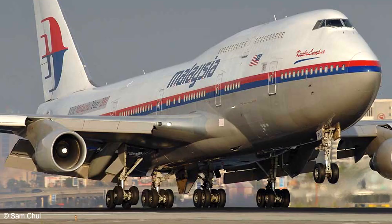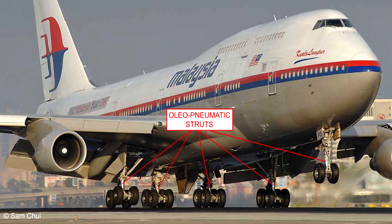A landing gear unit has to withstand various loads during its life. These loads are transmitted to the mountings in the aircraft structure, so these too have to be very strong. A landing gear is also subject to compressive loads, particularly during landing, but also whenever the weight of the aircraft is on the ground. The oleo-pneumatic strut helps to cushion these loads.